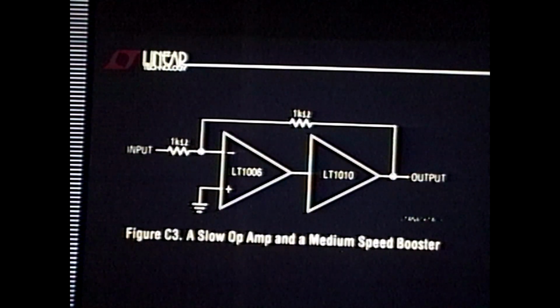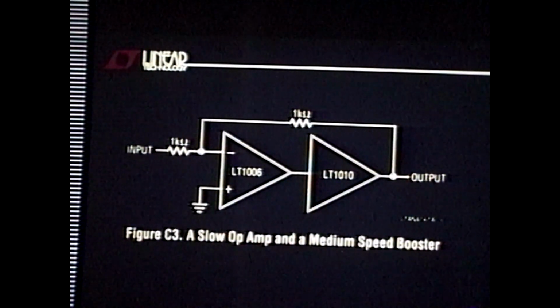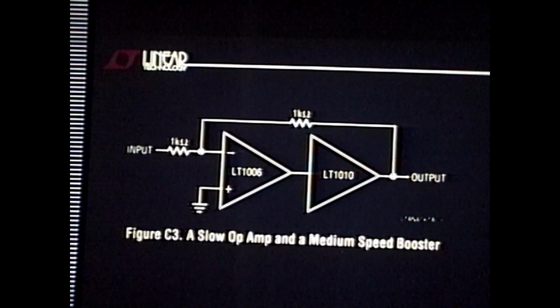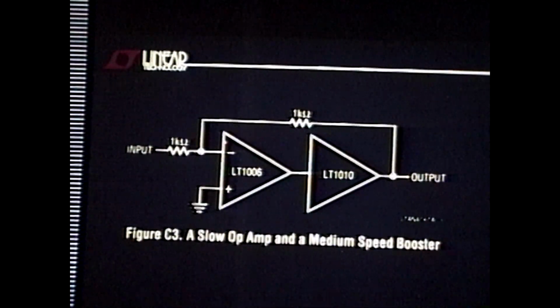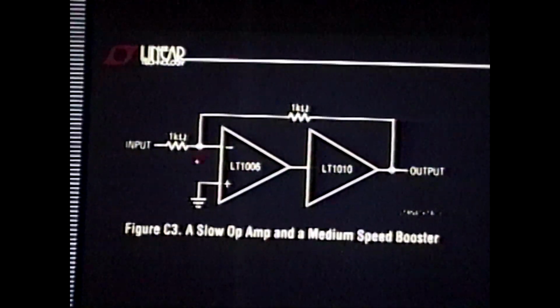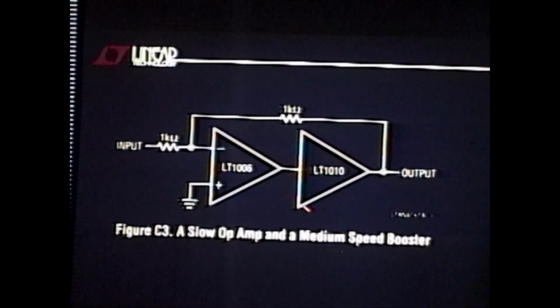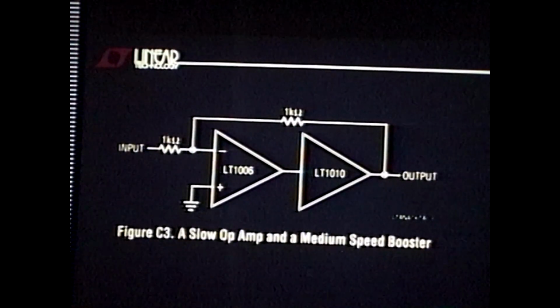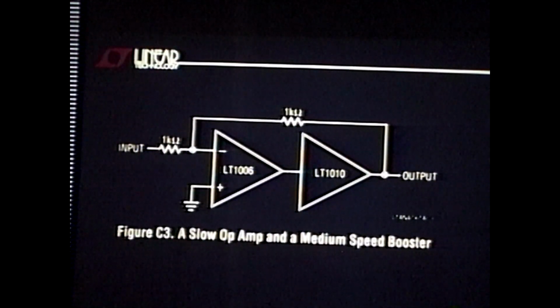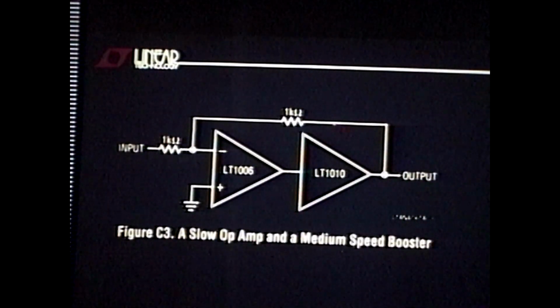Now what about loop stuff? Let's take a look at why loops oscillate at all with no mathematics. If I take a slow amplifier, in this case a 1 megahertz device, so that's a 741 class kind of speed, and this is about a medium speed 20 megahertz kind of integrated power booster. Your stomach tells you the following. This thing essentially looks transparent with regards to delay.